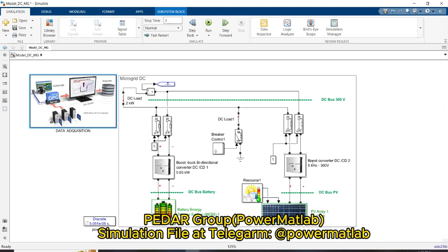As you know, the most important issue in each type of DC power network is controlling the stability of the DC voltage in the DC link. So we need a slack bus, or a voltage-controlling generation bus, to control the voltage in the DC link. For example, in this simulation, we consider these energy storage generation units to control the DC link voltage by absorbing and injecting power to the DC link power network for different fault scenarios in the system.